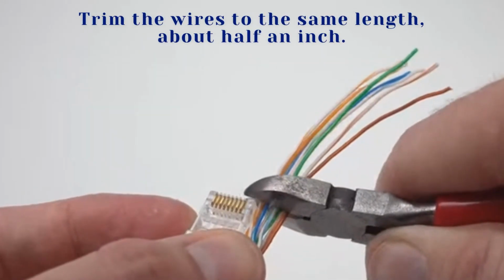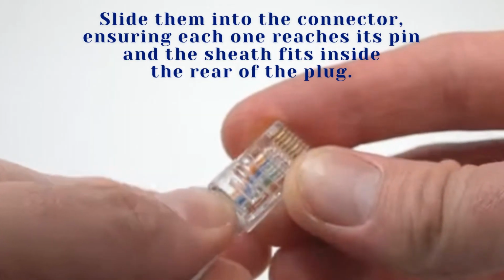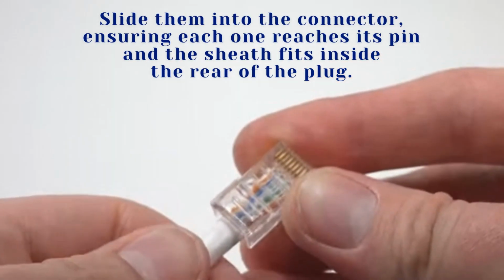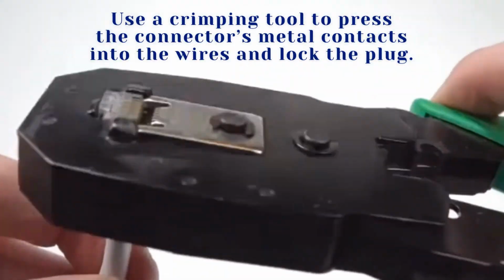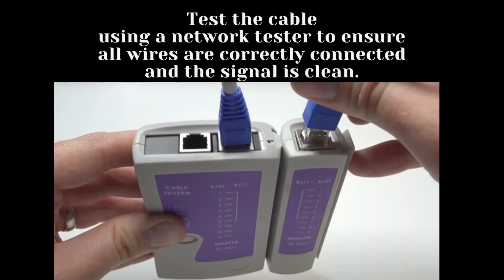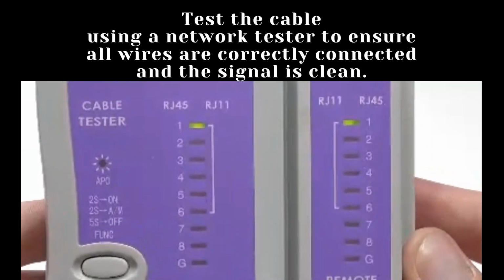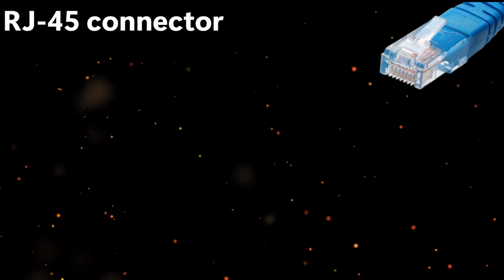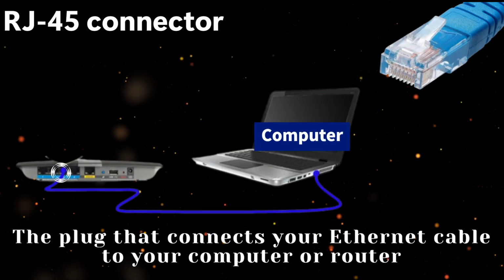Trim the wires to the same length, about ½ inch. Slide them into the connector, ensuring each one reaches its pin and the sheath fits inside the rear of the plug. Use a crimping tool to press the connector's metal contacts into the wires and lock the plug. After crimping, test the cable using a network tester to ensure all wires are correctly connected and the signal is clean. We just learned about the RJ45 connector, the plug that connects your Ethernet cable to your computer or router.